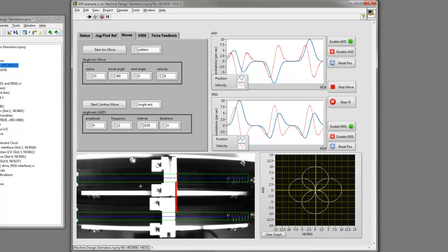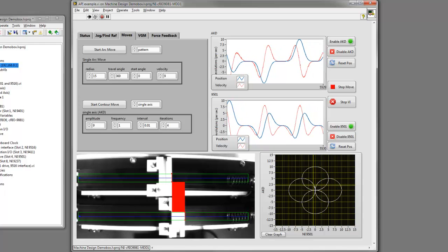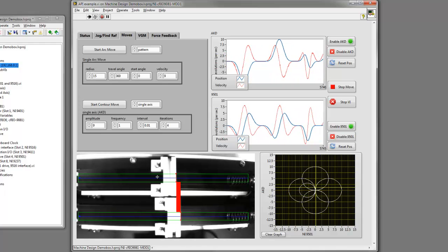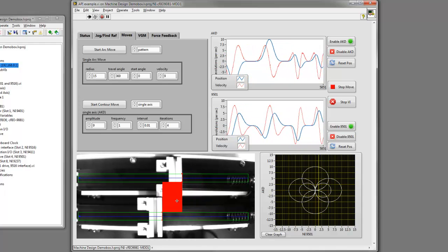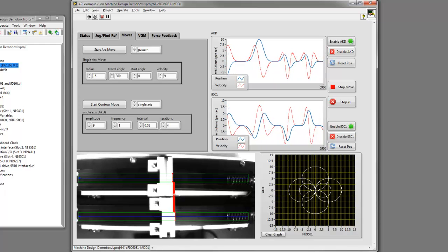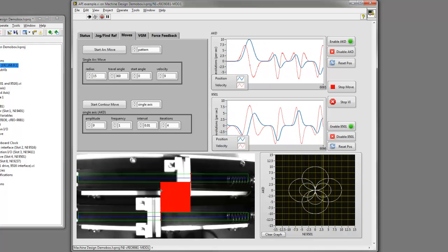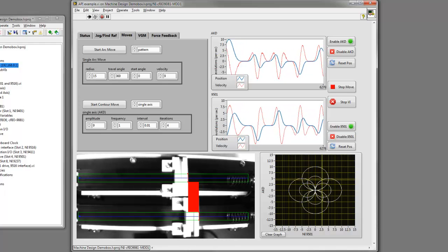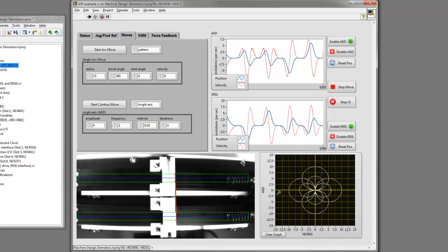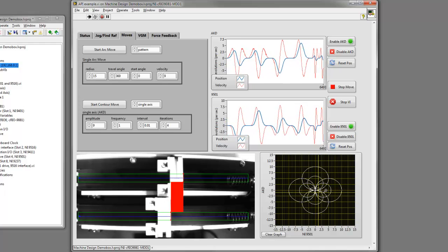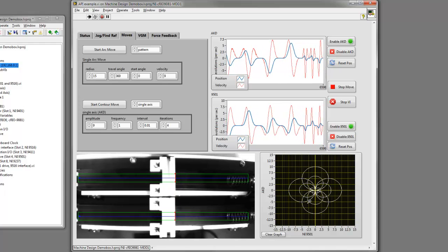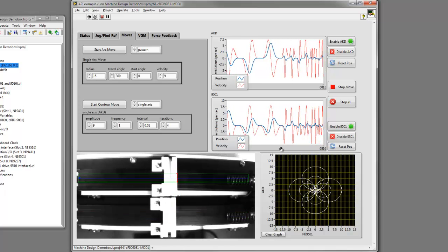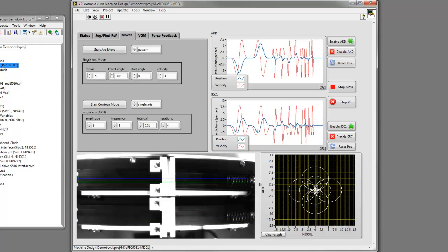And you can see my vision code is always running in the background, so I'm always computing the distance between these two front edges and these ROIs. I'm not using that information right now, but I am graphing and plotting it. I'll use this information when I go into my vision guided motion case. So you can see I'm doing consecutively smaller arc moves to do circles. Okay, and my move stopped.